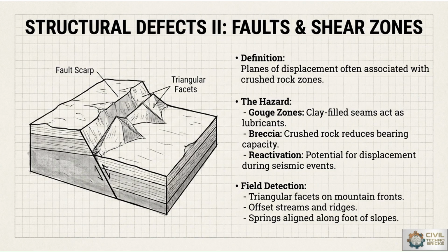Sheared rock masses generally have low strength and high permeability. Due to that, geological investigations determine fault activity, displacement history and groundwater movement below the earth surface. Weak fault zones require excavation, grouting, or relocation of the dam alignment as preventive measures, or we can say mitigation techniques.